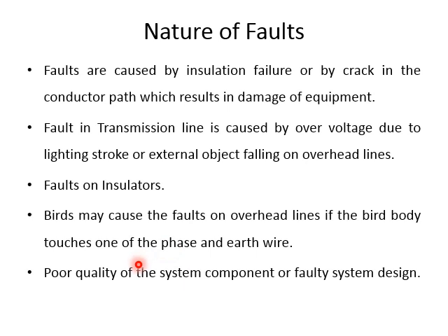Another cause is poor quality of the system component or faulty system design. If the connectors are broken, there is a failure of the connecting path and the connector becomes open circuited. If the broken connector falls to the ground, it results in a short circuit.